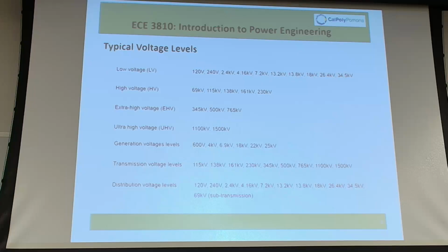And that's on the eastern side, the border with Canada, where there are quite a few now. By the way, there's a lot of buildup on 765. I have some pictures for you of a company that I work with that manufactures transformers, and they're building a lot of 765 for the Eastern Interconnect. A lot of companies are upgrading their 765 network, but that's as high as we go. And those are line-to-line voltages, remember.